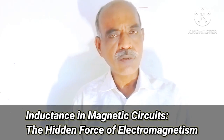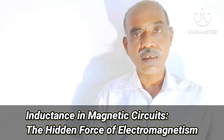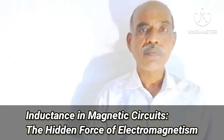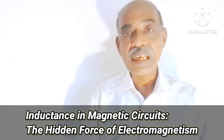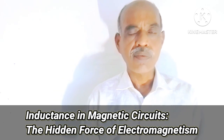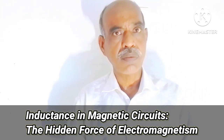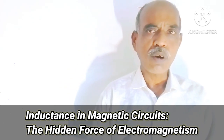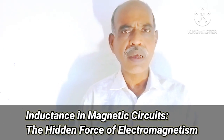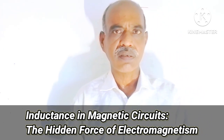In general, in transformers, air gaps are not allowed, because air gaps in any circuit increase the reluctance and thereby decrease the inductance. Again, if the permeability of the material is more, inductance will be more. If the number of turns is more, inductance is more. Just by analyzing the mathematical expressions for inductance, you can say all these things.